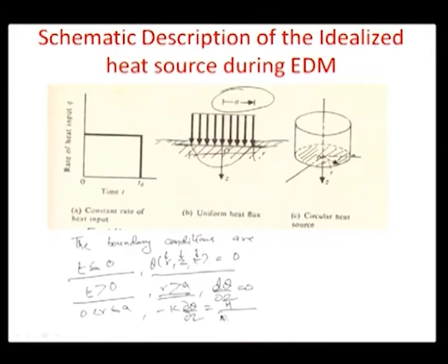So, it is the flux rate, pi a square times the time of discharge Td. We already have assumed H to be the amount of heat input, in calories. So, with these three boundary conditions, we limit ourselves to a very simplified solution of the equation which has been given in the earlier step, where the space time relationship of temperature in the melting zone has been correlated.